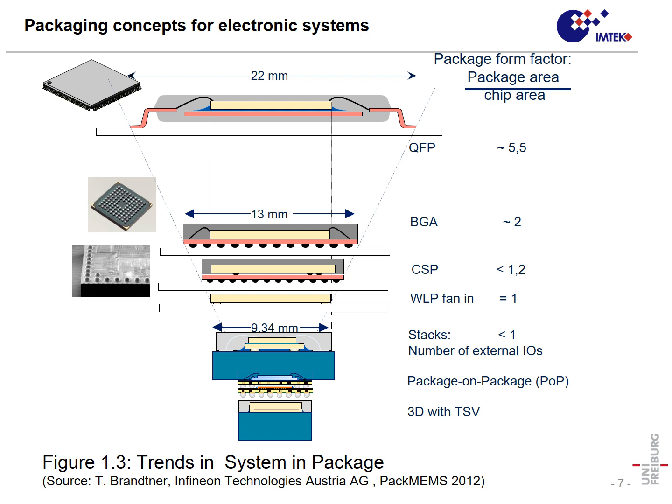And in that way, even individual devices would be extremely large. The solution for that was the so-called ball grid array. That means all the IOs which are first in a peripheral fashion are now sorted in a grid, and in that way a similar device only has an edge length of 13 millimeter.